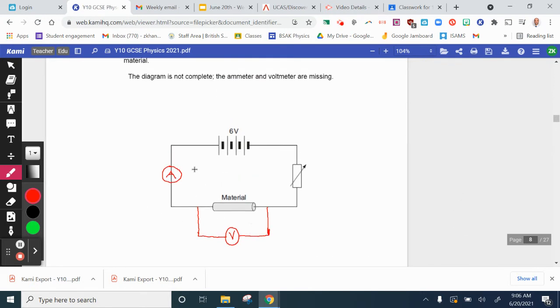We have a voltmeter reading and an ammeter reading. So the resistance has a direct link: resistance is equal to the voltage over the current. So if there's an error on the reading for resistance, how could we have got that? There could possibly be an error on the voltage reading, and it could be an error on the current reading, or maybe both. So there may be a random error on the voltmeter reading.